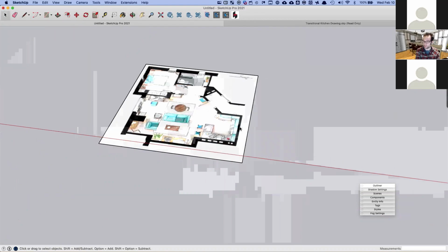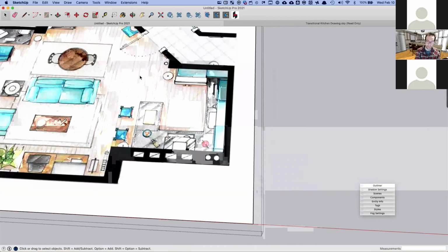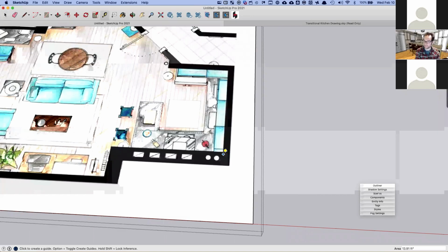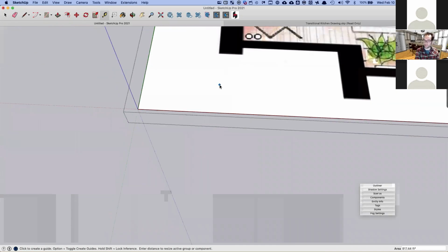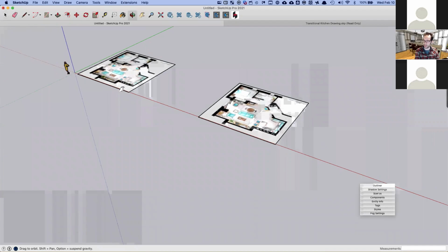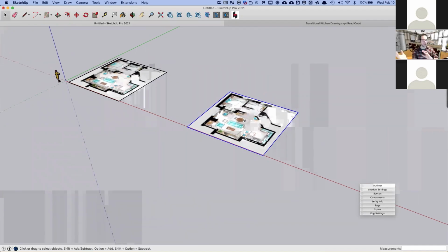You can just zoom in here, double click on it, click your tape measure tool, and click here and type 91.5. It will scale that as well, and it will scale it up to match. So it doesn't matter the imported scale. I like to sort of eyeball it and get it reasonably close, but you can do a finite scale like that.